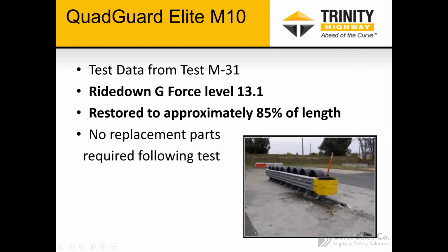Again, the maintenance guys will want to come in, pull this out further, stretch it to its original length. If you hold it in place about 15 or 20 minutes, that should be enough to get it to do that. But a lot of times these impact attenuators are not repaired the same day, or even sometimes within 2 or 3 days. Ideally that's the case, but depending on the situation, the maintenance guys may have a hard time getting to the site if it's in a gore area on a busy freeway, or they just might not have the manpower, or they may not be aware that it was impacted in certain cases.